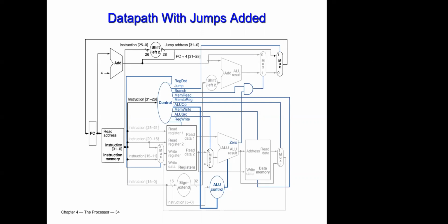As you can see from all of these, the controller plays a big role. Let's check this controller. This guy will choose whether I branch to a new address or I just go to the program counter plus 4. How will I know, from the previous information, that I have to branch? First, I have to do the subtraction, and the subtraction condition is satisfied, meaning the signal I called zero has to be 1.